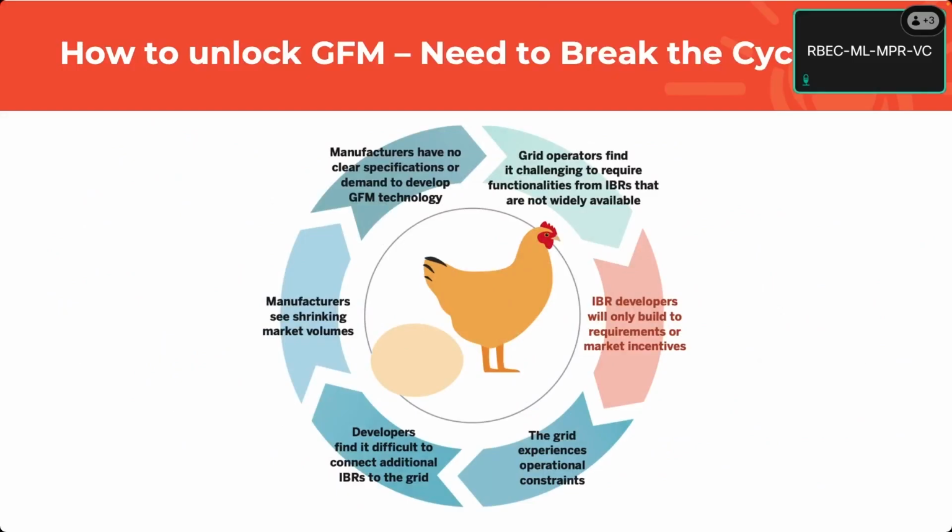I'm not sure if Unify is publishing that document in like a week. Well, it's been in a week for about 6 weeks now, but it should be about done in 2 weeks or so. And you'll see there's tiers of grid forming. But some of those tiers can be met with grid following devices with advanced tuning, like you're saying. But there are other tiers that you need these types of controls to do. So you can get a lot more grid stability benefit with advanced controls of grid following. But to go further, you need these grid forming controls.